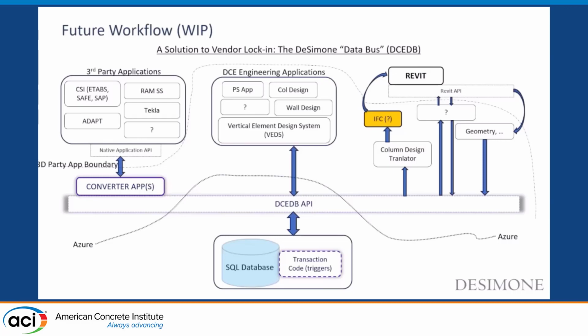It's storing all the finite element results on Azure in a standardized format, because various programs have different local axes definitions for columns and different sign conventions for internal forces. And so what we envision is that if we can get the column design in here, we can use IFC to pump it into Revit instead of marking up the PDFs like we used to do. So that's a description of a potential use of IFC in a column design workflow.